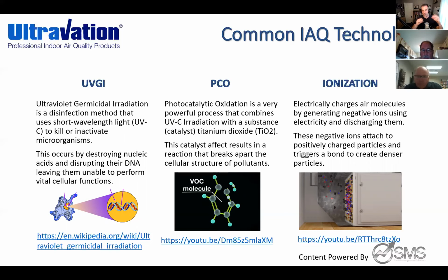So we have carbon, we have metal, whatever. Titanium dioxide is the catalyst element, and you need UVC wavelength light to activate it. And that's what creates basically an airborne field around the product when it's mounted in the ductwork, increasing your air disinfection rate, killing things, breaking down odors, deodorizing, all of that.